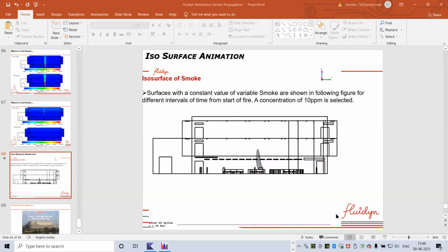But what I am trying to tell is that in case of fire, there is a large amount of thermal plume generated by the heat, which drives air also. The airflow is highly dominant, so the smoke tends to propagate along with the air in that case. For here, I agree, I don't have any problem. But when you say smoke in general, I have a problem, because I feel we need to change the solver up to the governing equations also. A state equation change is not enough. Of course. The case that he is trying to show is a fire inside a mall, so I think it's perfectly justified to use this gaseous approach in this case.